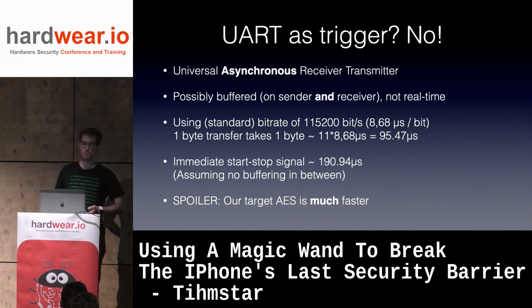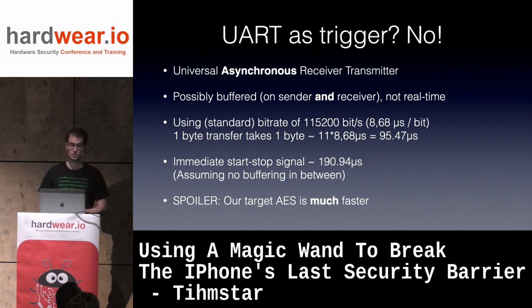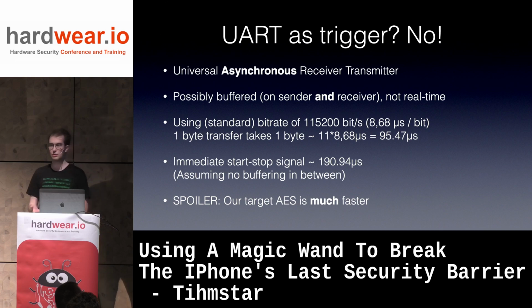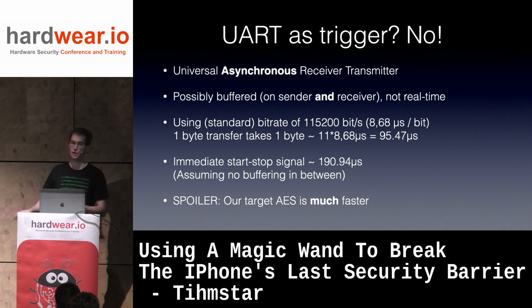Furthermore, if you use a standard bitrate of 115,200 bits per second, which is 8.68 microseconds per bit, 1 byte takes about 95 microseconds. Anyways, so if you send an immediate start-stop signal, which is like 190 microseconds, assuming there's no buffering in between, which there is, it's too slow. Our AES is long done by that, so that's way too slow.